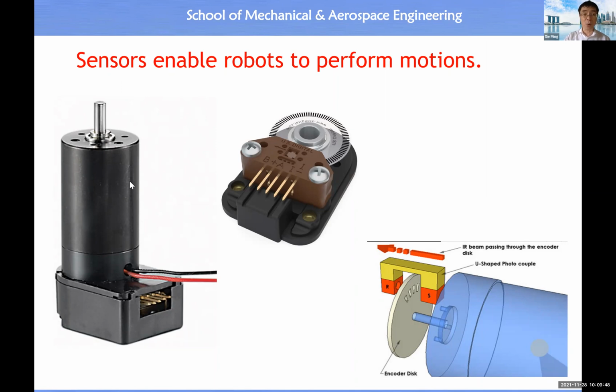So this is a power joint, and this is a velocity sensor with the capability of outputting position information. Once we open up this optical encoder, an incremental encoder, then you will see the inner components inside this sensor. There's a rotating disc, then we have a reading device to read out the optical pulse. Inside here, we also have the electronic circuit, which outputs the signal, digital information, through all these pins, right?